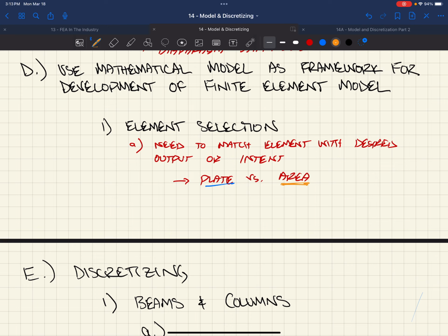And so an area is really powerful because it gives you this ability to spread loads to supporting elements, which allows you to change the beam configuration below an area, and it's going to automatically change how the loads are distributed. And you can decide whether the load gets distributed as a one-way load or a two-way load.